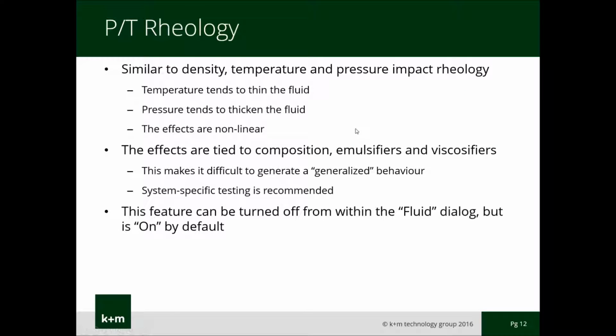Similar to the way density behaves, fluid rheology is also impacted by temperature and pressure. Increasing temperature tends to thin the fluid, and increasing pressure tends to thicken the fluid. These effects tend to be quite nonlinear. The overall impact of temperature and pressure is influenced by the type of base oil, the type of brine, and the type of additives that are used to build the mud. It must be noted that both oil-based mud and water-based mud rheology is impacted by temperature and pressure.